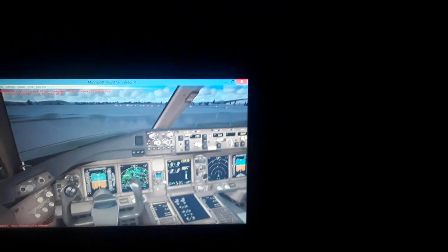I'm gonna show you the autopilot and flight director system panel, the MCP, that contains the autopilot engage and disengage switches, the auto throttle left and auto throttle right engage and disengage switches, the flight director on and off switch, the airspeed select knob. We're gonna select the desired airspeed for the aircraft. You can see inside the cockpit right now. So we're gonna select the airspeed mode.